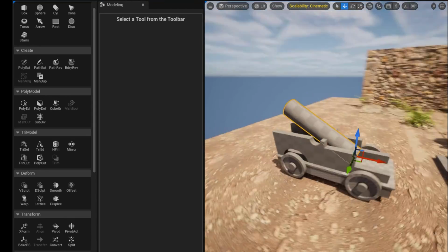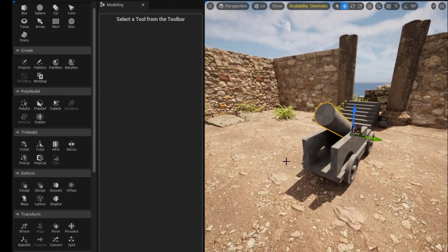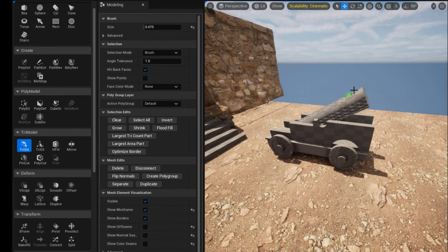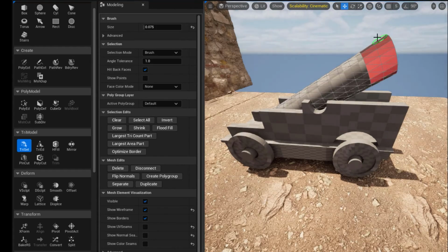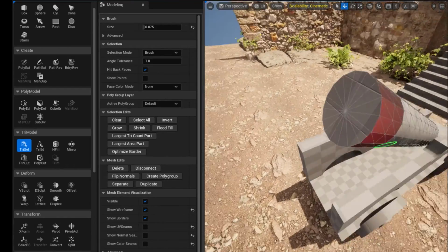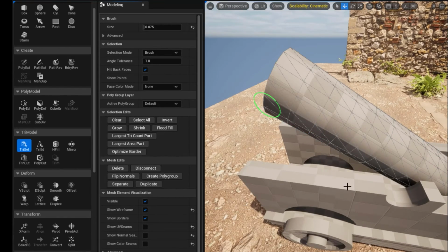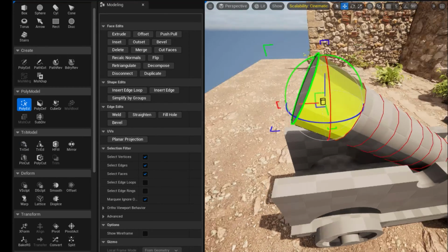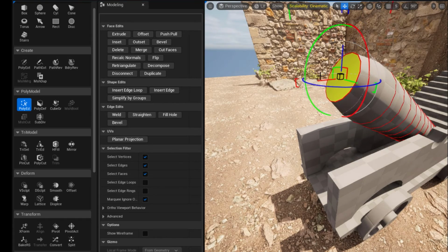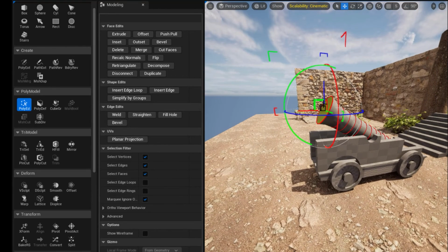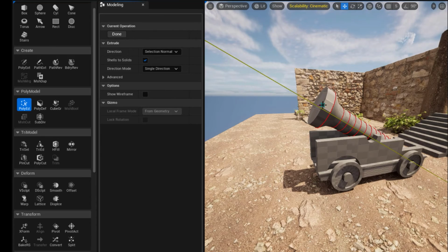In Freeform or Deformation, one of these lattices, I can just easily go in there, select a section and turn that into poly select. So I can just go ahead and select this area, select those really quickly. I'm going to have a look. Yep, it all looks good. Now I'm going to create a poly group. Now these two rings are one poly group. I can go in there and just shrink that bit or increase the height of that, or probably even exaggerate it and create an extrude like so.